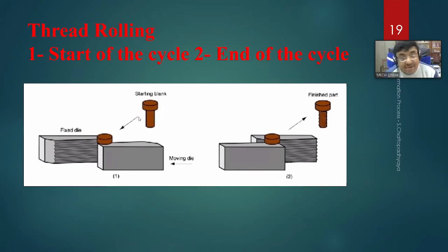You should not give the answer of a lathe. It will be just a mediocre answer. You will tell them 99.99% of the threads are produced by thread rolling. And a few here and there you can produce by lathe.